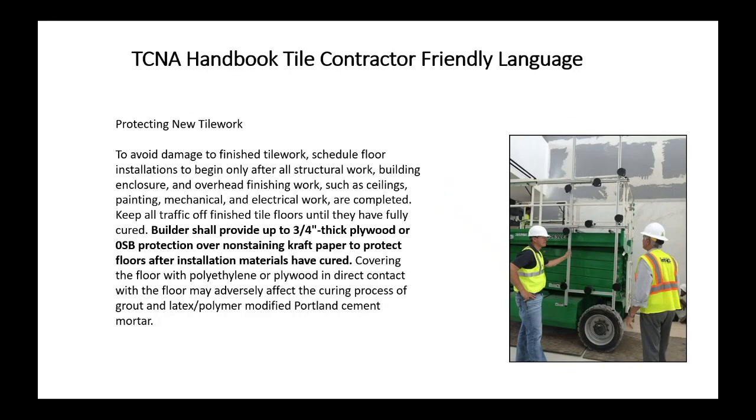Again, a little bit more TCNA handbook tile-friendly language, tile contractor language: protecting new tile work. It's stated in the handbook that to avoid damage to tile work, the floor should be protected, right? I mean, of all things, we want to make sure that the finished floor doesn't have construction materials going over it and so on. That when they're painting the ceilings or walls, that they're not putting overspray on top of your brand new installation.